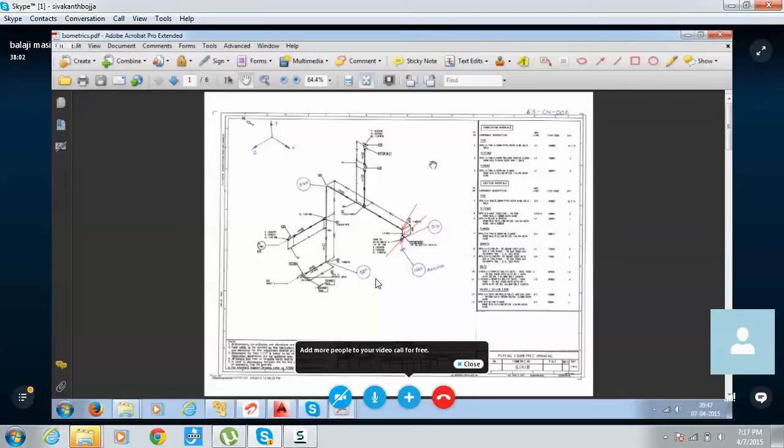That will be in the negative. So in the negative it will contract. Okay. We have to check the contraction and also expansion. Correct. So simultaneously it will act. So we have to check the minimum design metal temperature. MDMT. They used to tell. Minimum design metal temperature.